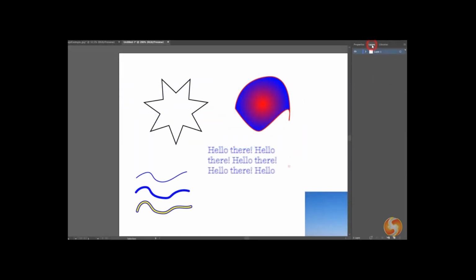With the Layers panel, you can manage the visibility of groups of objects called layers. By default, all objects belong to a single layer called Layer 1, sharing its same blue color on their skeletons. You can go to Create New Layer at the bottom to create a new independent layer and drop any object on it by clicking and dragging it. The skeleton will also change its color, assuming the same one of the new layer.